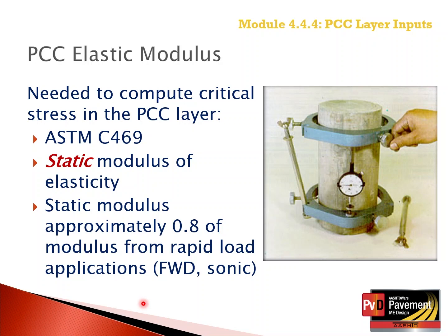So if the PCC modulus of elasticity is determined from rapid loading condition, that value needs to be reduced by multiplying the dynamic value measured from FWD or seismic or sonic means by 0.8 to be compatible with the inputs used in the global calibration process.